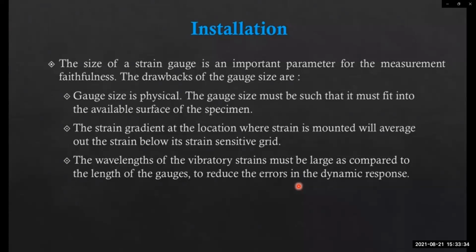The surface on which the strain gauge is mounted must be very smooth so there are no errors, and all the stress applied on the test material is measured accurately. All scale, rust, paint and other surface contamination must be removed from the metal surface. So we frequently need to clean our strain gauge, right?